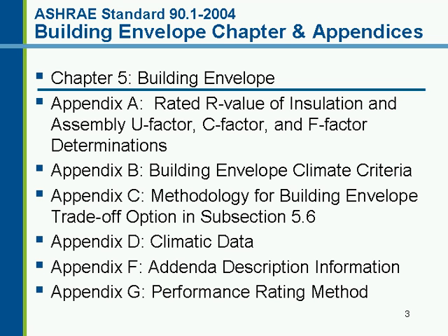And finally, Appendix G. This is a methodology that's been used in a number of green building rating programs. So if you wanted to claim a certain percent energy savings beyond Standard 90.1, this establishes the baseline. Within this, it's got the baseline for the building envelope criteria.